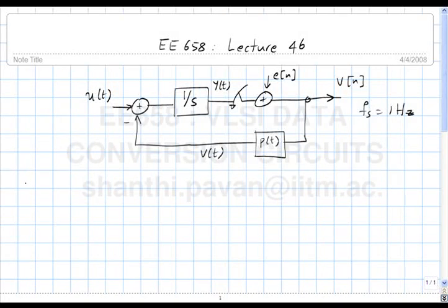The in band frequencies are basically 0 to 1 by 2 OSR, right, because Fs is equal to 1. Now, in a conventional Nyquist type converter or an oversampled converter operating on samples of U of t already, what all frequencies will alias to this band?